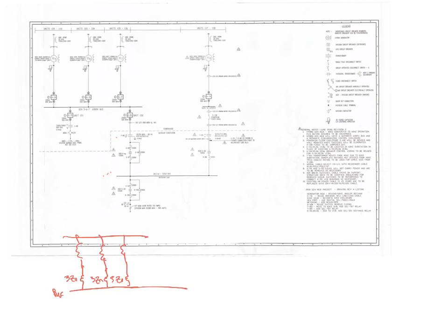And now I'm at bus 1. Okay? So we'll just call these Z0s. And you got that. Now we're going to go to bus 2. And we said that we're connected from bus 1. Because I don't have a ton of room, I'm going to put this connection here, which is not going to connect to bus 2, right? It's going to hang in the air. And this connection is bus 2, which does have a connection through the transformer to reference, right? So you can see here, there's no connection between bus 1 and bus 2 because of the delta.